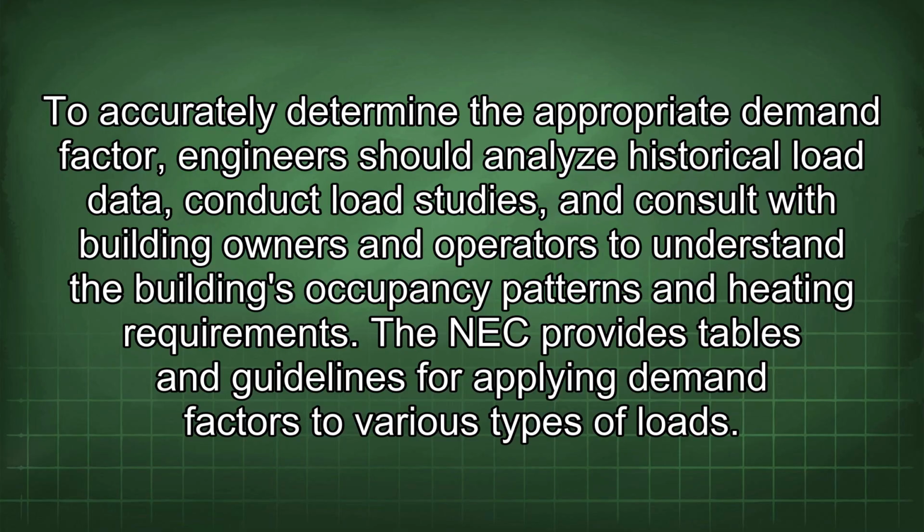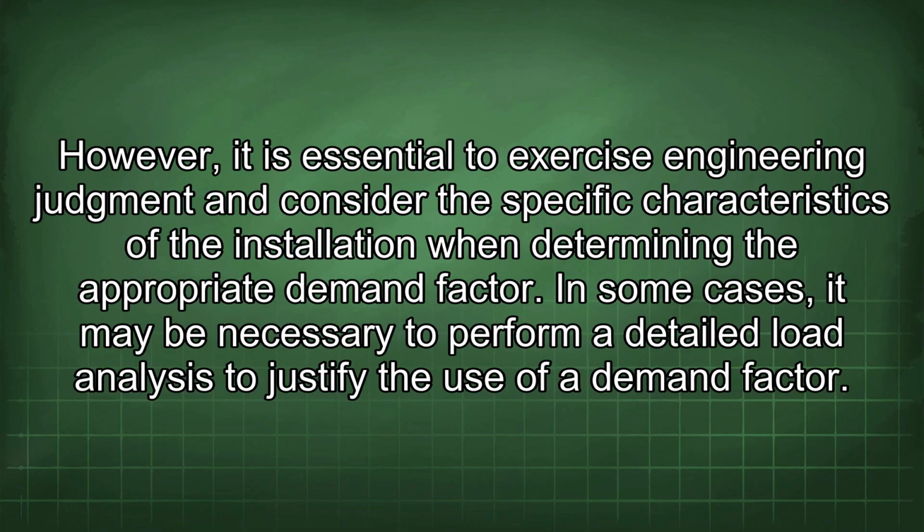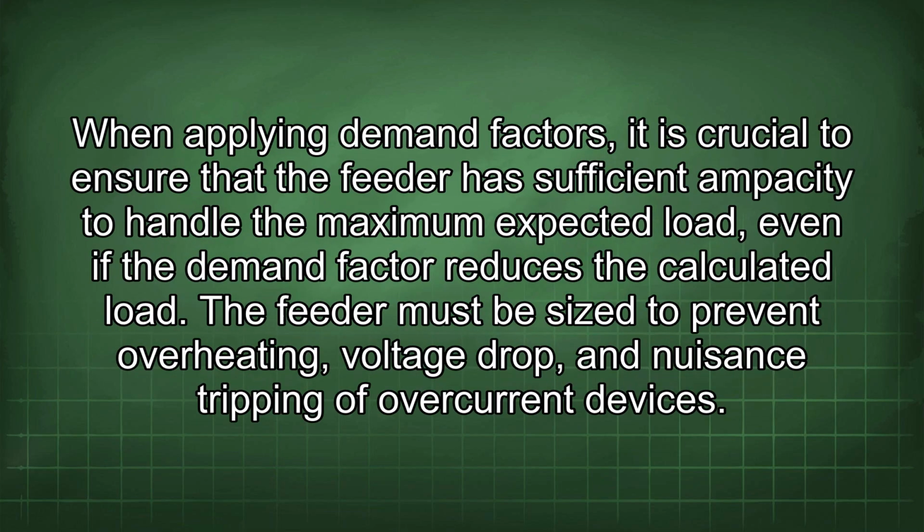The NEC provides tables and guidelines for applying demand factors to various types of loads. However, it is essential to exercise engineering judgment and consider the specific characteristics of the installation when determining the appropriate demand factor. In some cases, it may be necessary to perform a detailed load analysis to justify the use of a demand factor. When applying demand factors, it is crucial to ensure that the feeder has sufficient ampacity to handle the maximum expected load, even if the demand factor reduces the calculated load.